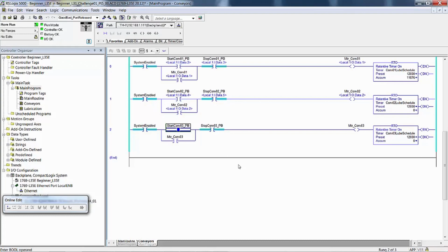Notice in the instance when I moved the rungs that the 2 timer instructions appear to be enabled. They are not actually enabled, but were left this way when copied and pasted from the main routine. In other words, that last execution of both timer data types was that they were enabled, so those 2 bits are still on in the controller's memory, which is totally isolated from the logic. If the logic doesn't execute, the state of the memory stays the same.